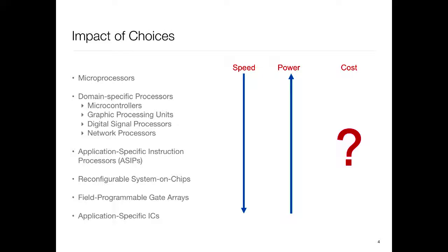Let's say I'm NASA. I'm designing something, and I'm designing one of that. So for one of that, I'll go and buy a processor, and whatever these processors may be, anywhere from $1 to let's say $1,000, depending upon what type of processor you're looking at. But that's what I'm going to pay. Whereas if I'm out here, designing my own, then I have to pay for all that design effort and masks that go into making chips and all the non-recurring costs and stuff like that. So that first unit is very costly out here because here I'm riding on the large market that exists.